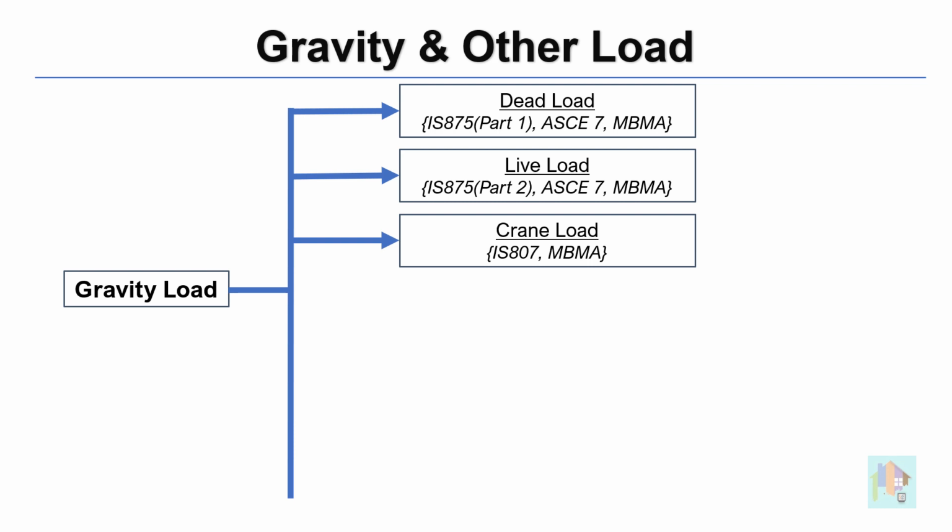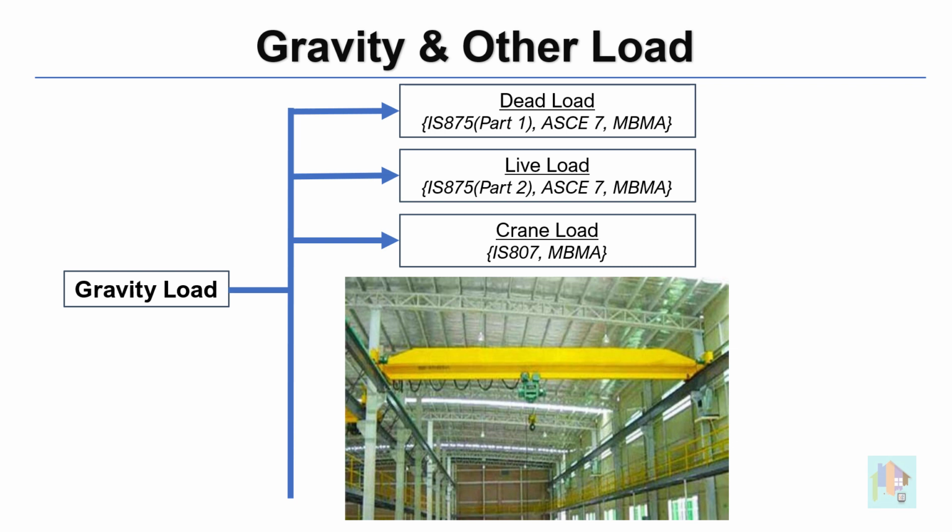In any manufacturing or plant unit, medium to high capacity cranes are used, and it is very important to consider the crane load during analysis and design. Though it is nothing but a dead load of the crane unit plus maximum load capacity, still we don't consider this along with structural dead load. Crane load is not a static component. It moves along two horizontal axes, and depending on the location of the crane, load distribution and bending profile change.